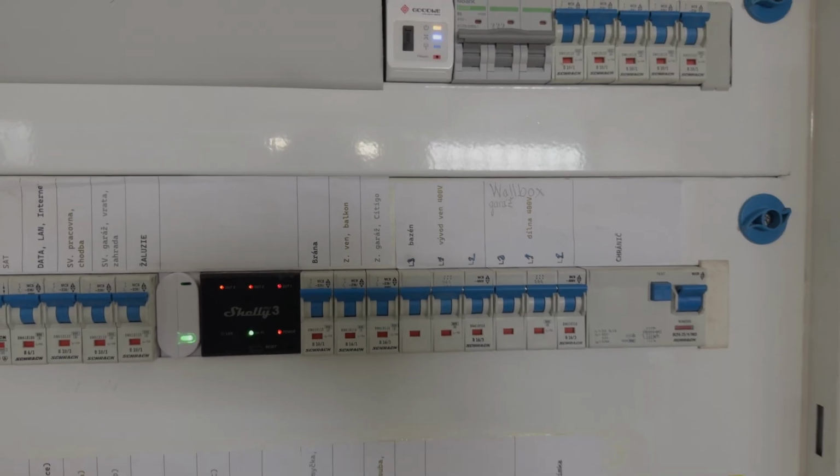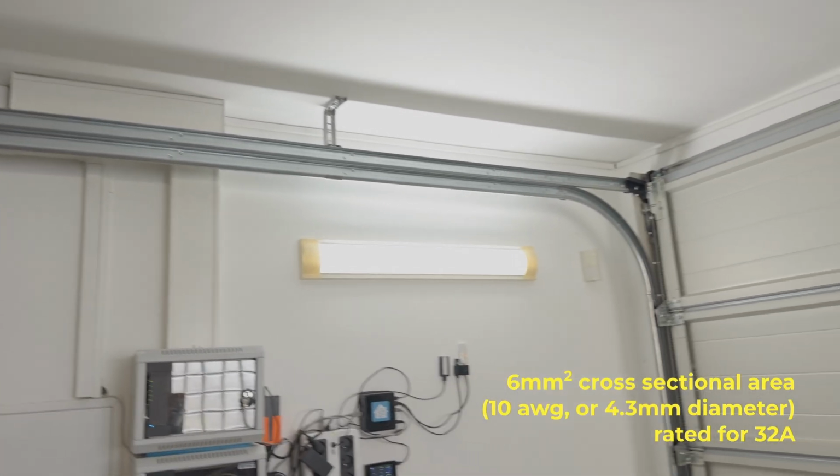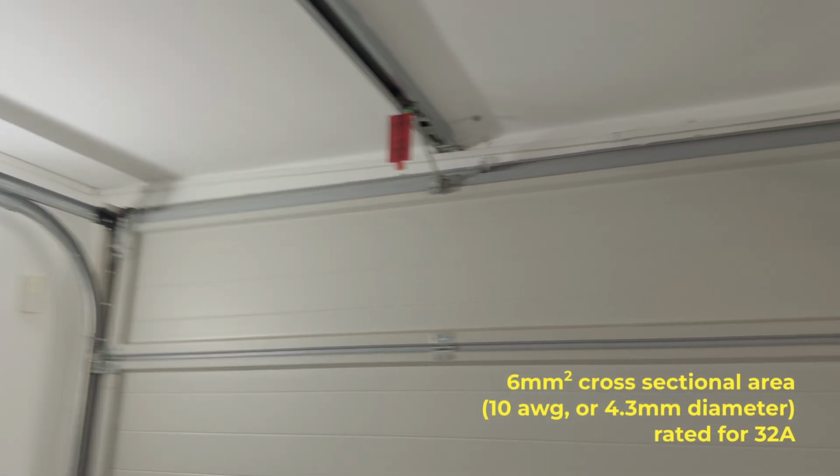Anyway, so let me show you the setup. I connected the wallbox to a dedicated 3-phase 16 ampere circuit breaker. I'm using a 6 millimeter cable. That's by the norm, because the wallbox consumes power all the time, so they use this general diameter to make sure it doesn't overheat. That said, 6 millimeters is really thick. It will be okay for 22 kilowatts with a reserve. For 11 kilowatts, 4 millimeters would be fine. But anyway,